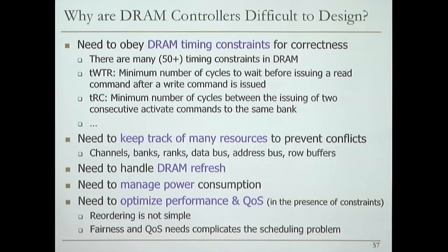And batch mode makes sense because you want to minimize, amortize these dead cycles on the bus, right? Because this TWTR means that you cannot do a read access to the bus after you do a write access. Okay, so that affects your performance clearly, and that affects your quality of service. So you need to optimize it as a memory controller. And that reordering is not simple.